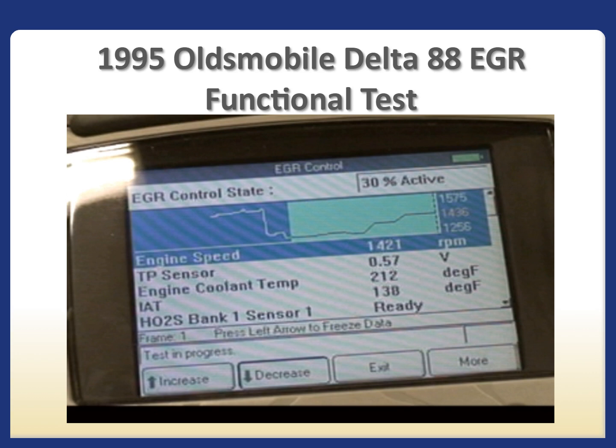Not all scan tools operate in the same manner. The EGR test shown in the previous slide indicates that the Tech 1 scan tool will automatically cycle and open the linear EGR valve from 25% to 100%. The scan tool in this video does not automatically cycle the linear EGR valve. The inspector will have to manually cycle the linear EGR valve from 0 to 100% to achieve the same result.